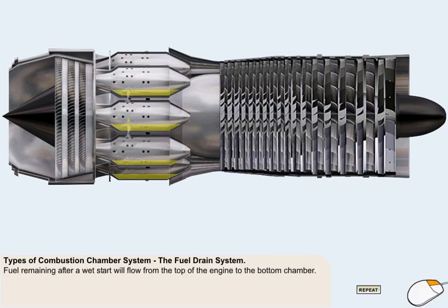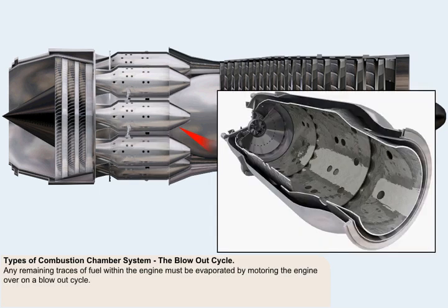Fuel remaining after a wet start will attempt to find its own level by flowing from the top of the engine to the bottom chamber. Once in the bottom chamber, the excess fuel exits the engine. Any remaining traces of fuel within the engine must be evaporated.